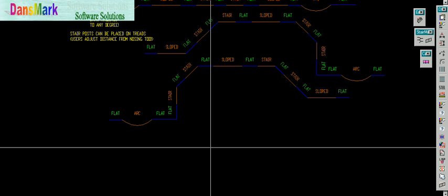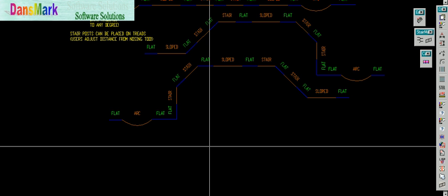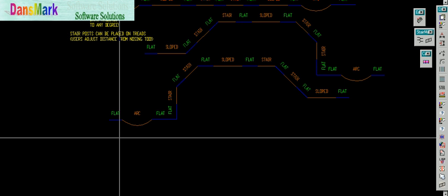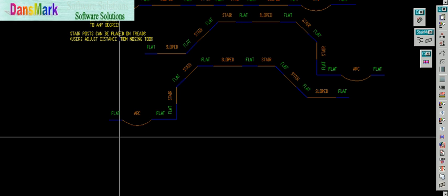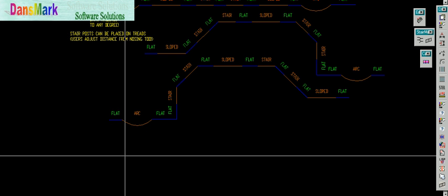We're going to do an E or an erection drawing. We're going to do a flat. You can either pick a distance or you can enter a distance. We're going to do a pick, and then we're going to start them out at that point. So vertically, that's where they're going to be drawn. And then we're going to either go left or right. We're going to go right for this particular one, and we're not going to put any dimensions on it, and we're going to do another one.